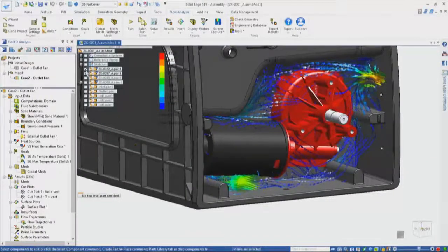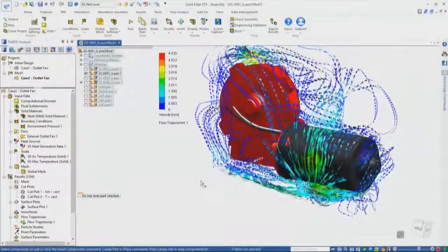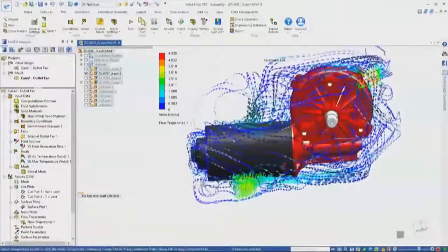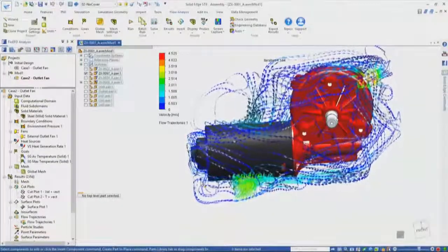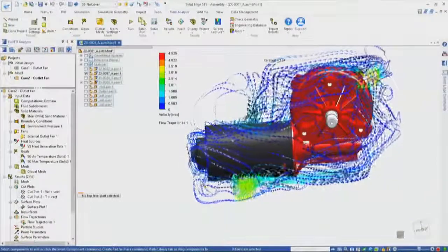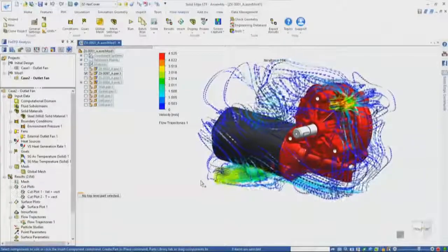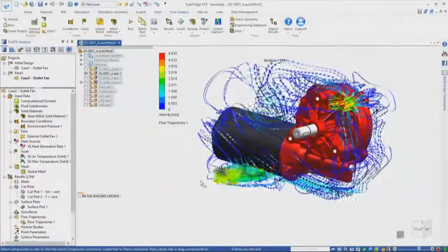And one thing, as I set this up and ran it, if I look at it a little bit from the front again, there is still flow that goes along the floor, as in the first case. But then after that, it still has to be dragged up past the motor on the right-hand side there to get to the fan exit. And I think in doing so, that's what's able to take more heat off of that motor, and it's what brings down the temperature in this second case.